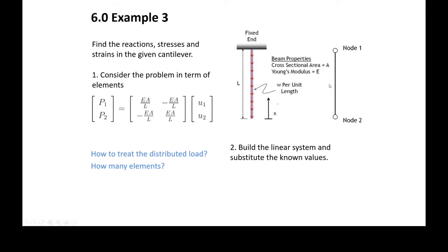We have two suggestions. Kamal suggested we take the resultant: we have the distributed load, small w, multiply w with L, have the resultant force and place it at this end here. And then Chloe suggested we do the same, but place it at mid-length. I think what Chloe suggested is probably more reasonable. I mean, if you move the entire force and put it at this free end, it is going to be a bit extreme. But if you put it in the middle, this would be more representative.